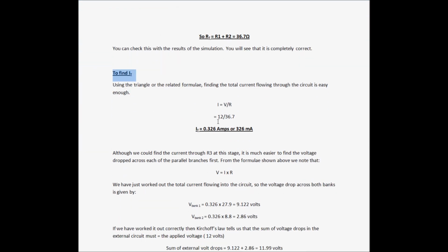To find IT, we use I is equal to V over R. R we've just worked out, that's RT, and V is the applied voltage, which is 12 volts as mentioned earlier. When you do that sum, you will find IT is equal to 326 milliamps.